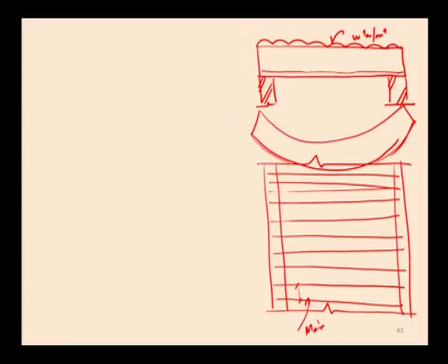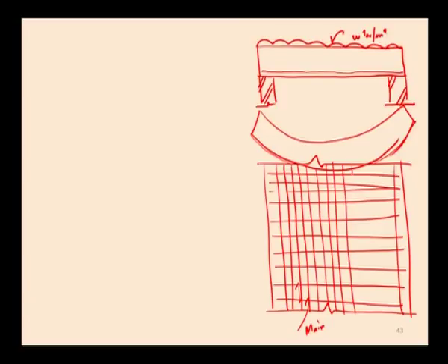This reinforcement has to be properly placed with proper spacing. In order to keep the proper spacing of the reinforcement, reinforcement should be provided in the perpendicular direction, which is used to distribute the main reinforcement with proper spacing. That perpendicular reinforcement is called distribution reinforcement.